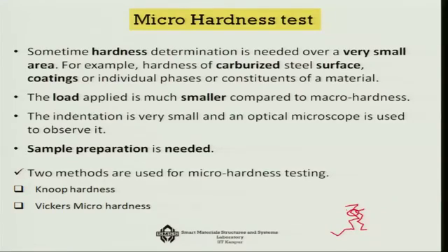There is a continuous contact between the two. So, on this kind of surface, you must give a special coating on the teeth of the gear. You give a very thin coating layer, which is very hard, to save it from wear and tear. Now, for this kind of very thin coating layer, you cannot really use the macro hardness tests. You need a micro hardness test for doing it.